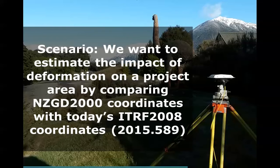So the scenario that we've set up here is we've got a project area that we're interested in and we want to estimate the impact of deformation on that project area by comparing some Datum 2000 coordinates with today's ITRF2008 coordinates. So ITRF is the latest version of that global reference frame, and by today's date, specifically, I'm meaning 2015.589, which happens to be the 3rd of August.